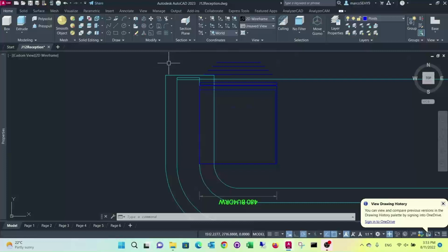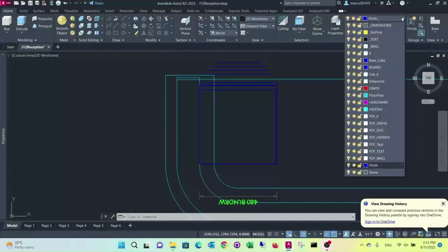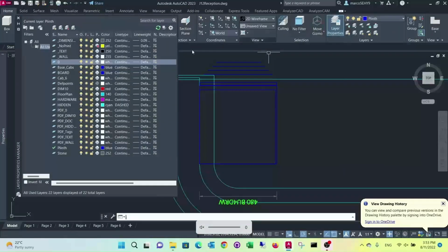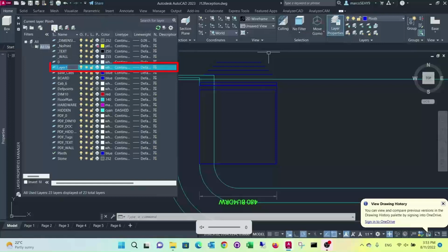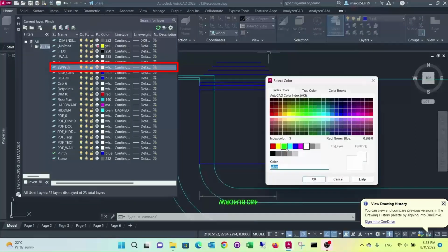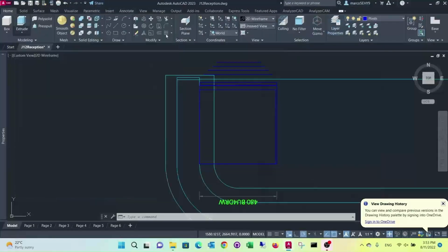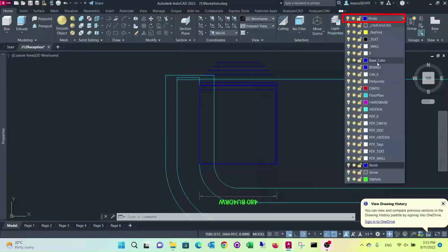The next thing to draw is the sweep path. We use a polyline for this and create a new layer for the polyline to sit in. Let's call it SW path. Make the layer a distinctive color like green, so it will stand out. Make that our current working layer.